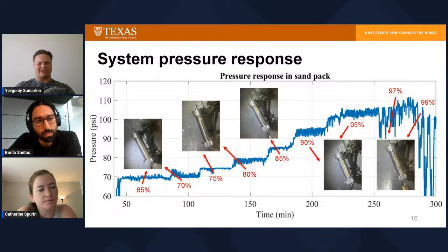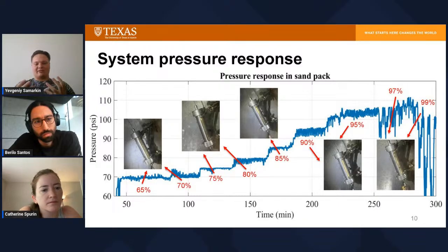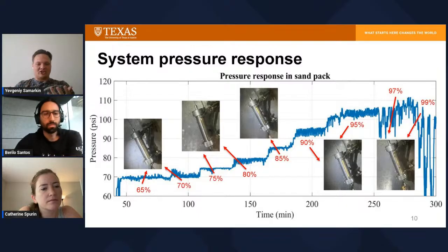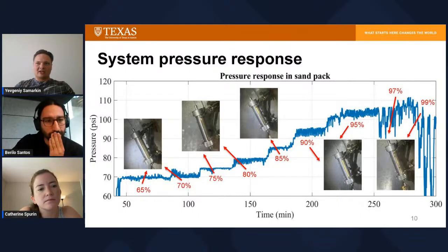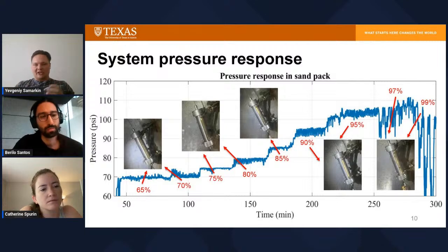So our quantification is basically limited to the rheological curves that we have, because it's a high temperature and high pressure environment, and we cannot have more visualization rather than just those pressure measurements. But from the consistency of the experiments, we continuously see that the foam that we generated in that layered formation was more viscous. So that tells us something, that something different is happening in that specific setup.